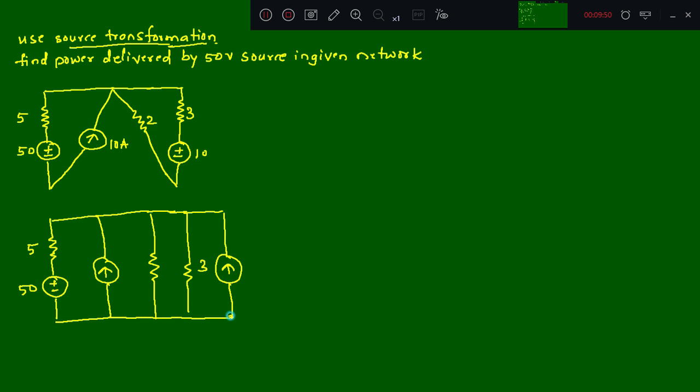What is the I value here? So this is 10 amperes, this is 2 ohm, and then I will be V by R. Okay, so 10 by 3, so this will be 3.33 amperes, right? So further, what simplification can we do here? You can observe here, this 10 ampere current source and 3.33 ampere current source are in parallel. So what is the result out of this? It's the addition of these two.